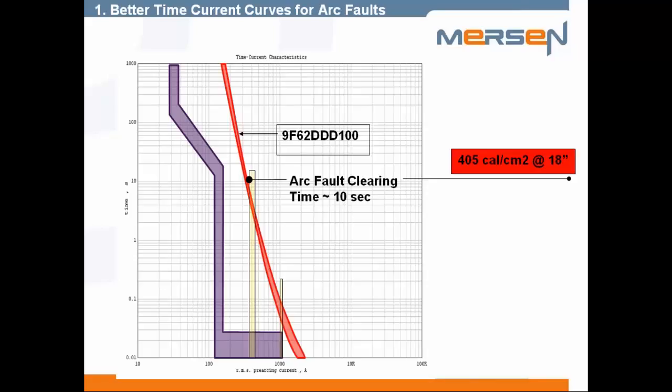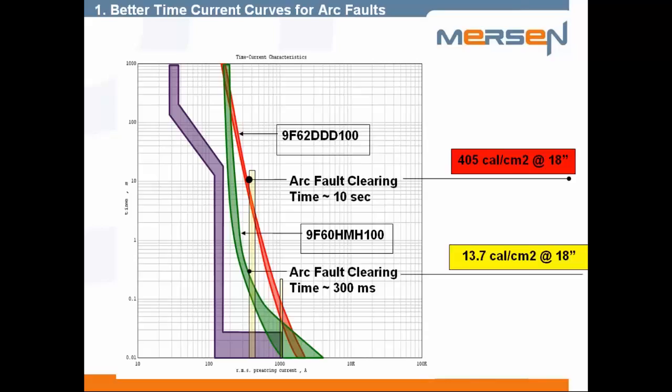If you replace that with a fuse curve that's less inverse and make sure that it passes the inrush currents, you'll find that the clearing times are much faster in this region. For bolted fault currents, it would be near the same. But with these types of substitutions, you can get Category 3 levels of PPE might be appropriate, but it still requires a flash suit.